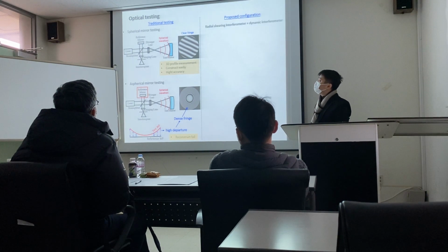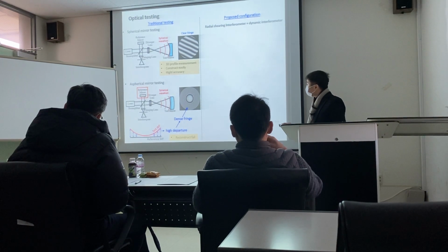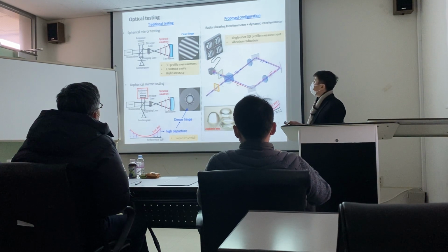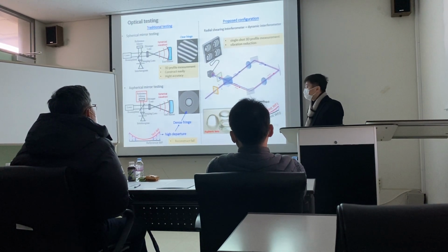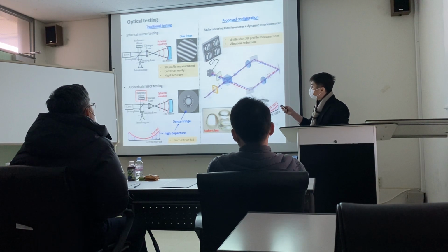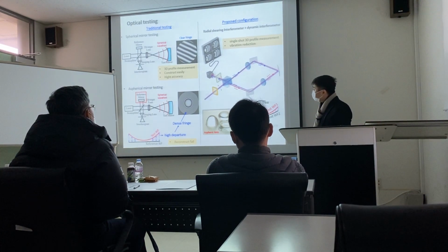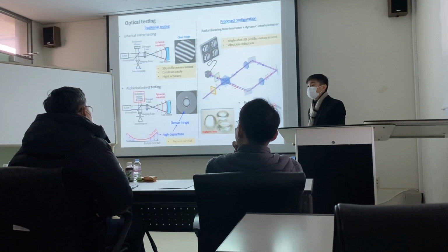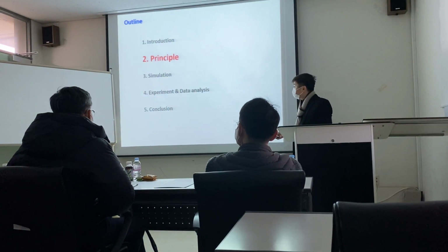In this study, we propose a radial shearing interferometer combined with a dynamic interferometer. With the advantage of the dynamic interferometer, we can get a single-shot 3D profile measurement, removing much of the vibration in industrial environments. With the reference-free characteristic of the radial shearing interferometer, we can reduce much of the departure. This is a very low-cost way to develop a high-accuracy system for aspheric testing. So let me talk in detail about the principle of that method.